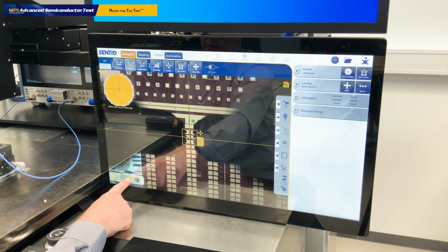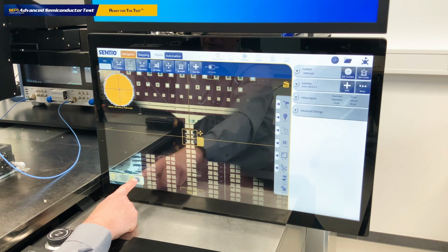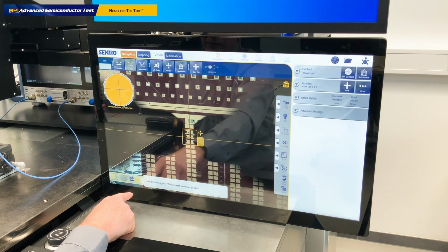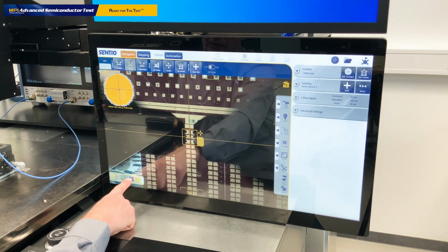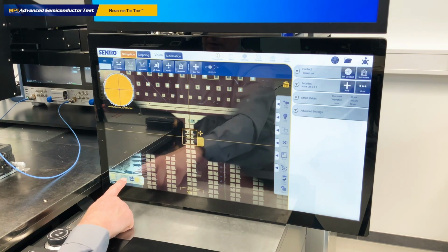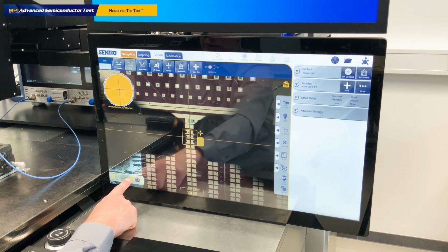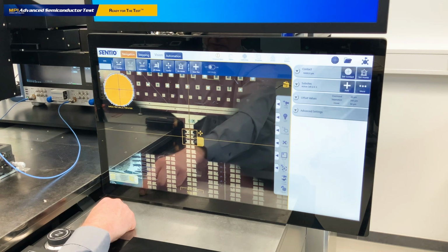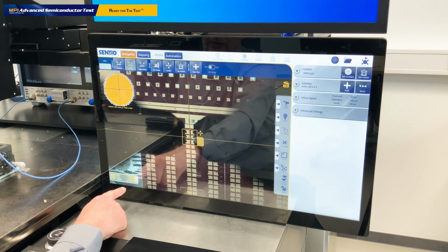The next selection is user-defined, so you could always say, okay, I want this current location to be my user-defined origin, and then SENTIO switches the coordinates of X and Y to reference from the current location. But also you can change to Z, which means the lower left corner of the movement area is now the reference, and SENTIO gives you absolute coordinates.